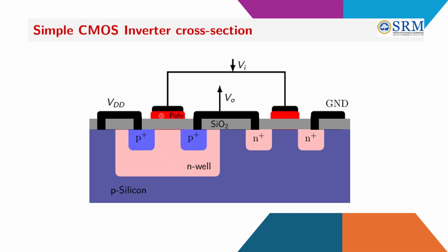Then use etching if required, right? Then development of your drain and source using the diffusion technique. While you are developing the polysilicon, you can use lithography, then metallization, and then at the end of the metallization, the annealing process to check whether this is correct or not.